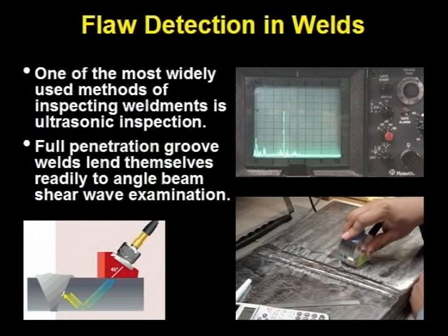Angle beam inspection is often used for flaw detection in weldments. The top bead of the weld is often too rough for normal beam contact inspection. The refracted beam can be aimed approximately normal to the heat-affected zone of the weldment, which often contains cracks. Applying this technique requires considerable skill, as the transducer must be oscillated towards and away from the weld while simultaneously understanding that the sound path length changes. The transducer also needs to be translated parallel to the weld.